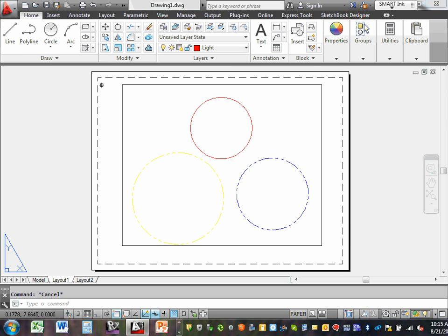Here's what happened in the past. The students will turn the lighting layer off, then the viewport is gone, and they say, I swear about the viewport. Well, the viewport was in the wrong layer. So it's very important to check and make sure which layer is up. So typically the viewport, we put it in its standalone layer. Everybody's okay with this?